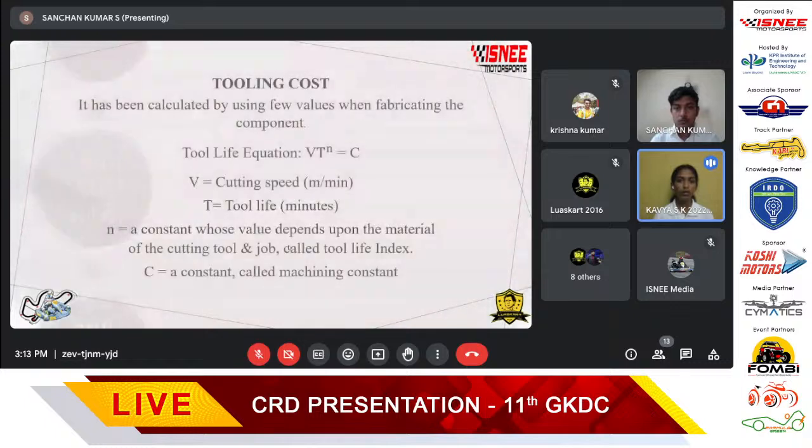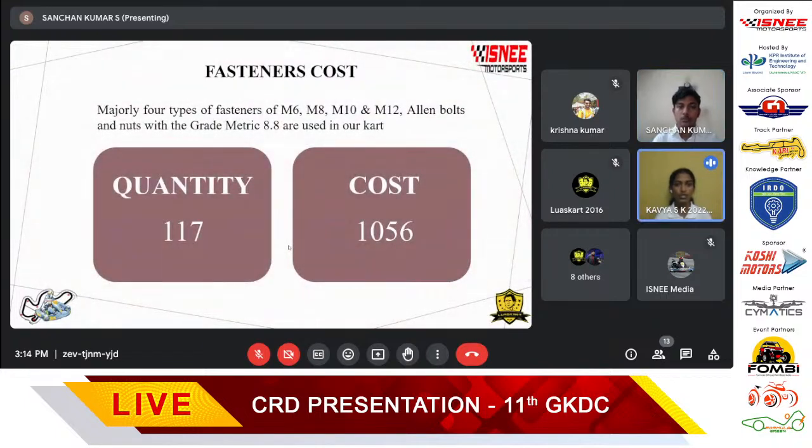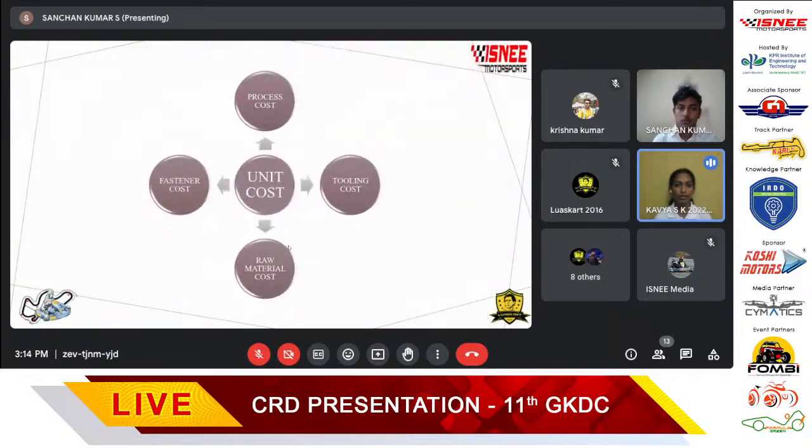First, looking into the tooling cost, the tool life equation used is V T to the power N is equal to C. The factors considered while calculating the tool cost were depth of the cut and the time taken. Coming to the fastener cost, a cart mainly comprises four types of fasteners, which are M6, M8, M10, and M12. Also M16 was used for the pillow block. Allen bolts and nuts were used with a grade metric of 8.8. The quantity of fasteners used was 117, and the cost comes around 1,056.